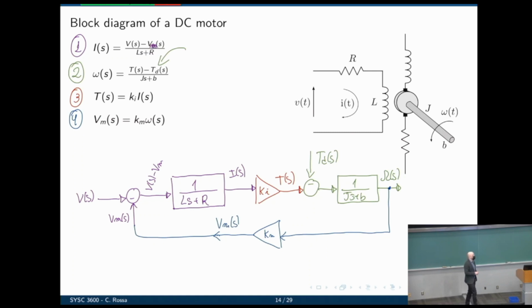Let's take this one step further and calculate the position. How do you do position from this? How would you use this to calculate the position of the motor? We do the integral of speed, and how we do that in the frequency domain, we simply multiply that by 1 over S. That's now the position of the motor. If you simulate this and look at the current, something interesting happens.